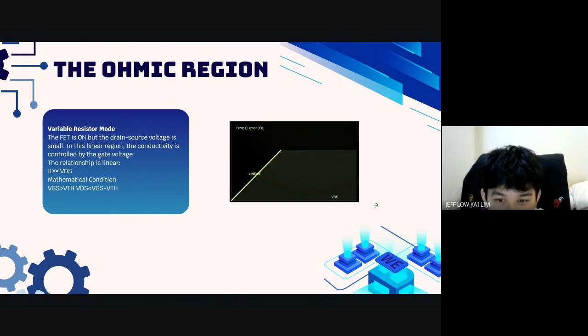Next is the ohmic or linear region. Here the FET is on, but the VDS is very small. In this state, the FET acts like a variable resistor. As you can see on the graph, the ID is increasing linearly with the drain voltage.